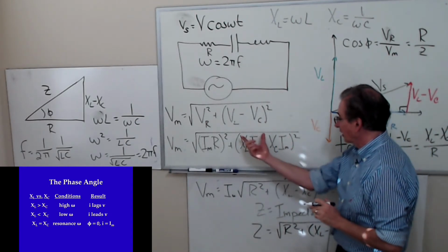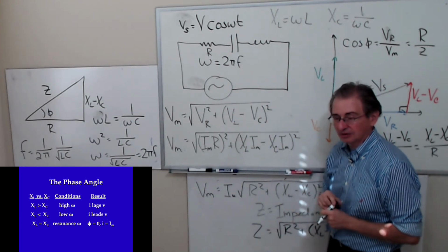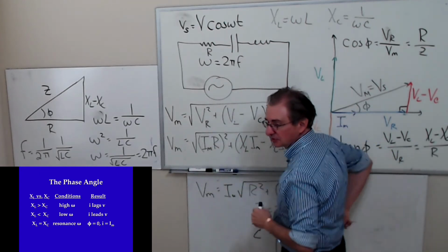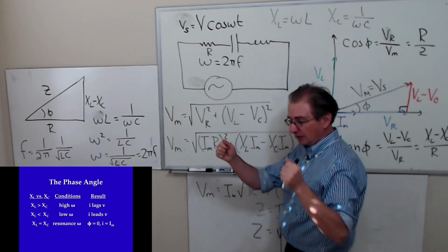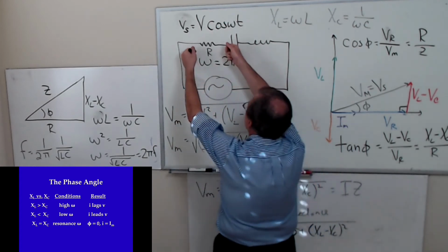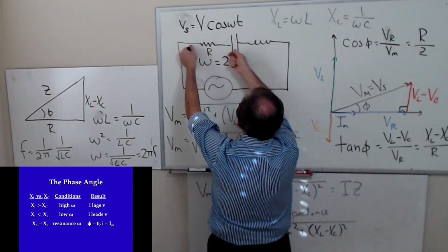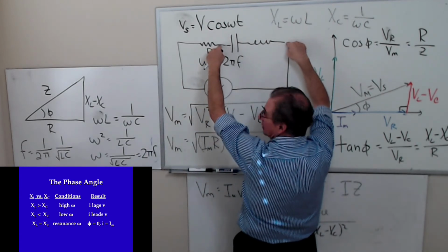Like I said before, it doesn't mean that either one of these is 0. It just means they cancel out. And it's possible that these voltages are bigger than the power supply voltage. But if you actually take a voltmeter and measure the voltage across here, measure RMS voltage, and then you compare it to here, the voltage between these 2 points will be 0.